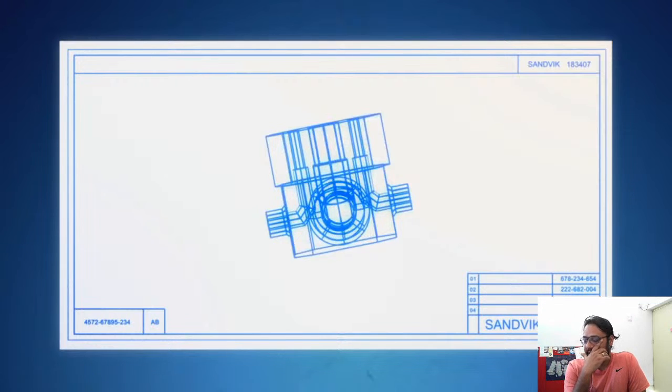The idea of a near net shape is that let's say the final part has a lot of screws and holes and whatever is required to assemble the part, right? So you remove all of those features which can be easily made with other processes, so they need not strain one process altogether, even if they can possibly be done. So you remove those features to get an overall shape.